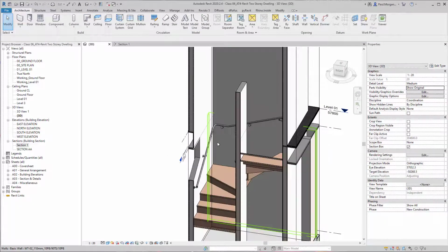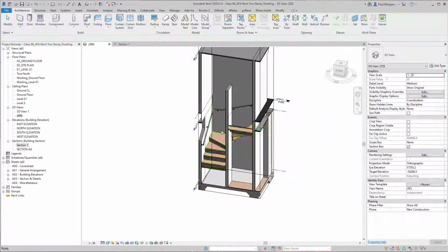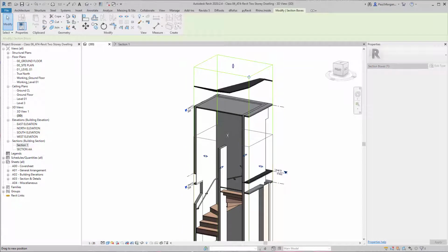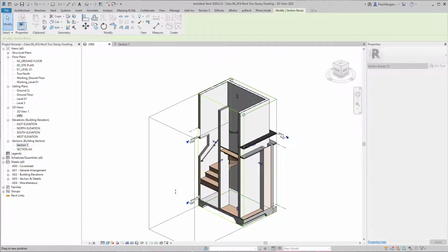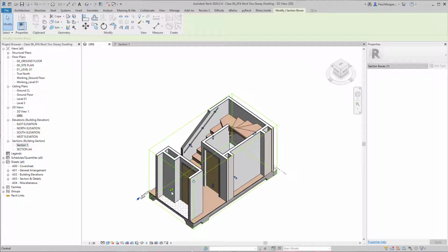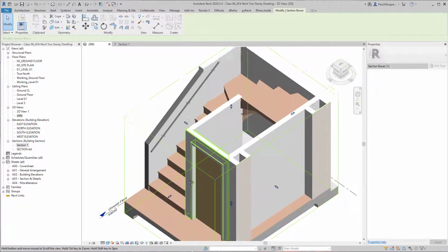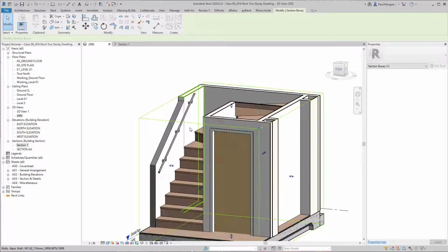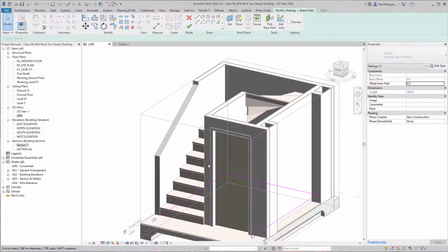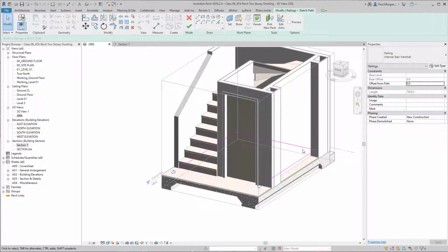But what I'm going to do is just edit this sketch path, just so you can see what you can do with sketch path editing with Rails. So I'm going to move this back, bring that down. I'll move this in as well. You can see how powerful the sketch tool is. The section blocks tool is. So I'll click on the handrail, and then I'm going to click on edit path. And what happens is you get this U path like this.